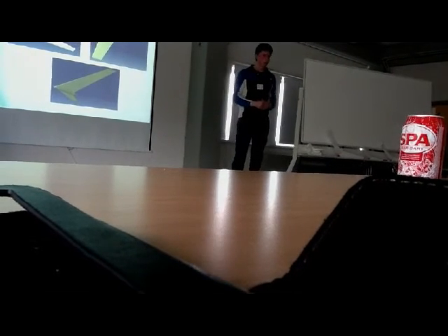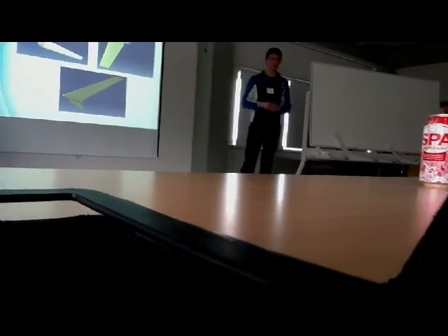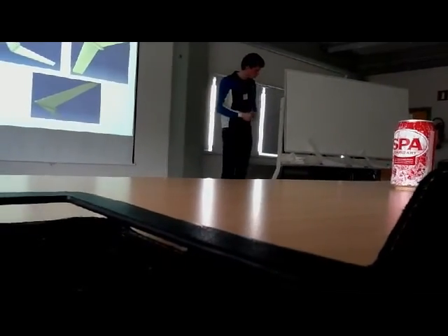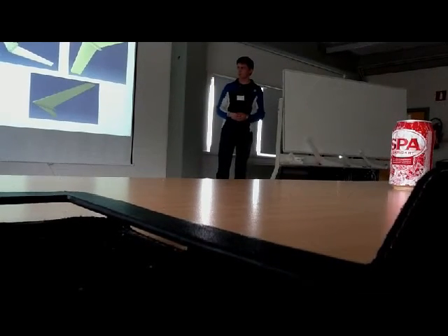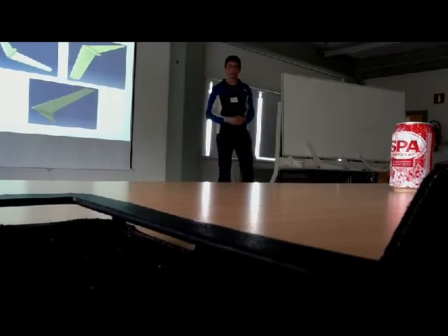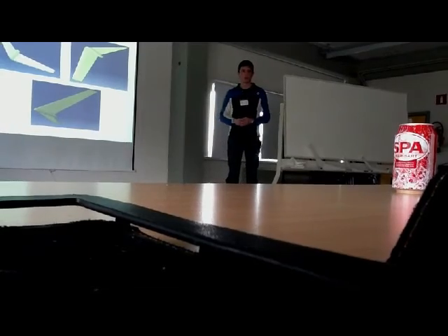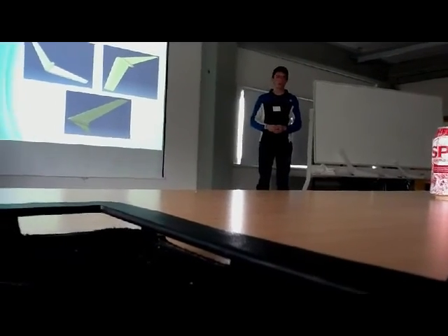So we decided to increase the sweep angle from 20 to 25, and then we made the other model that is more stable. Then we checked if this first approximation was right with, as you said, the aerodynamic software, that confirmed the stability numbers.